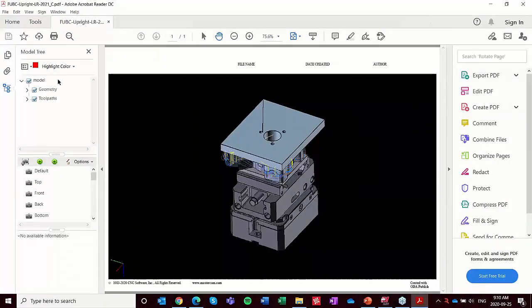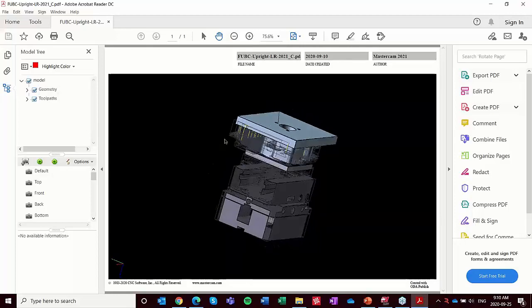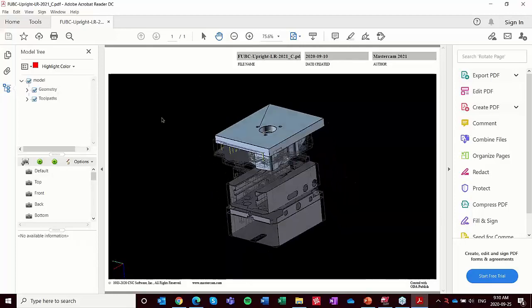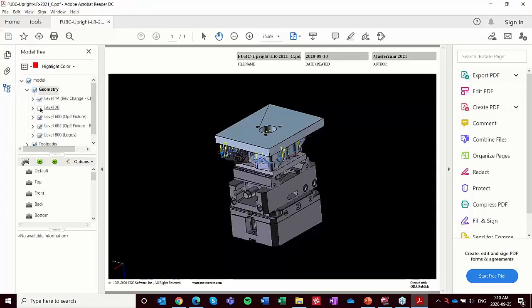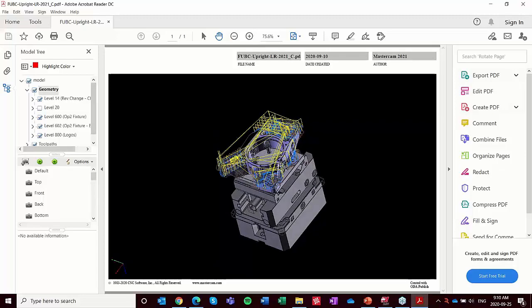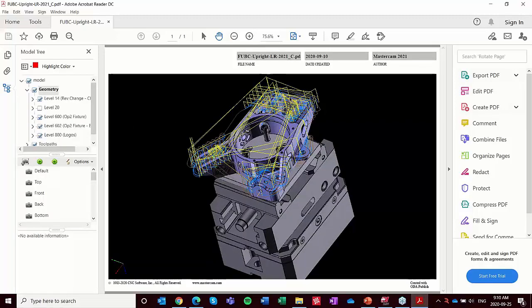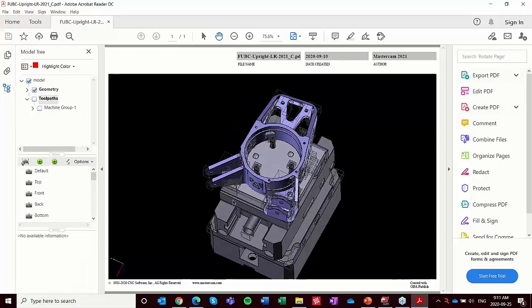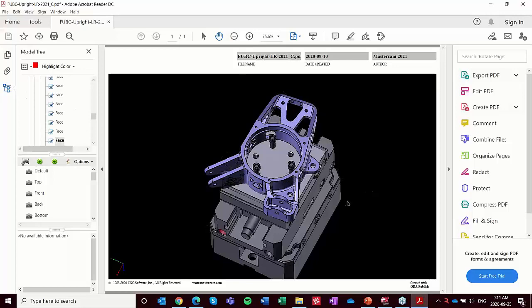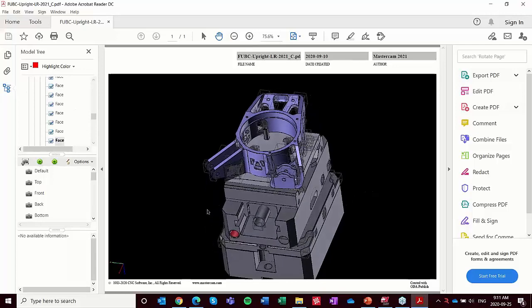So in the past, some of you guys used our Home Learning Edition to be able to view what's going on on the shop floor. This is now another good alternative to see your geometry and your toolpaths as applies to that. Andrew, can you maybe turn off that top piece there? So we can turn off and on all of our geometry levels as well as our toolpath levels to have a look at what toolpaths are being run and how the geometry tree is being affected there.